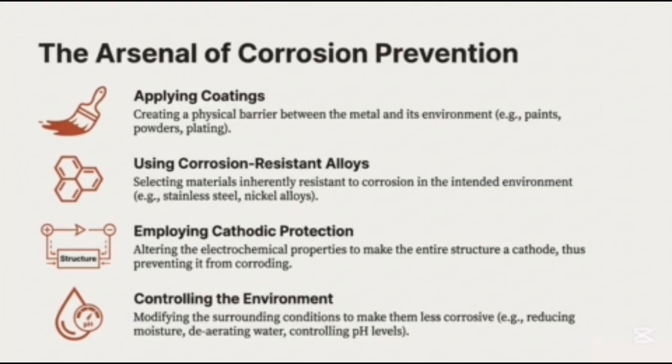The third method, and it's very useful, is to apply a cathodic protection material. This method works by placing a material other than the material we want to protect from corrosion. This material we place is a reactive material, as the reaction occurring in it is faster than in the material we want to protect.